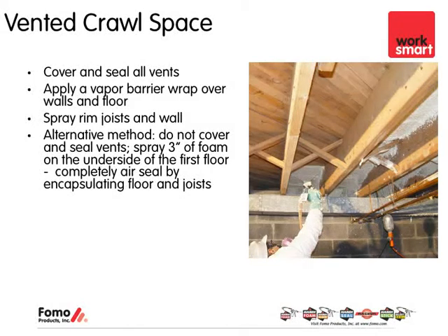So in essence, you're insulating the walls just like you'd be insulating the walls of the home, because this now is a conditioned crawl space. You need to have some insulation in there. And as code would require with polyurethane foam, you'd probably want to put some form of an ignition barrier, which could be an ignition barrier type paint, or another type of barrier, depending on what code would require.